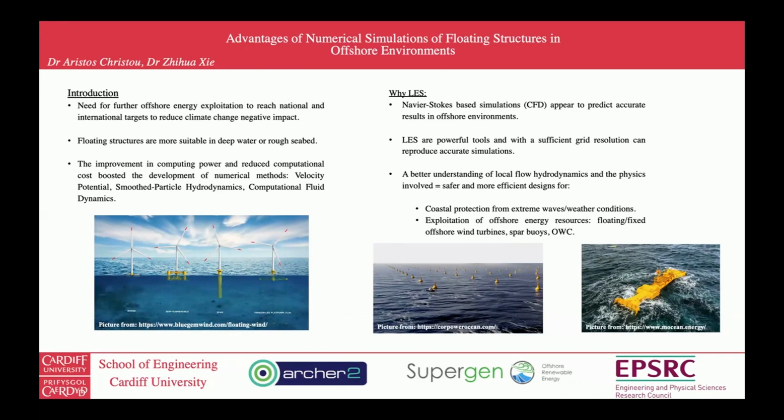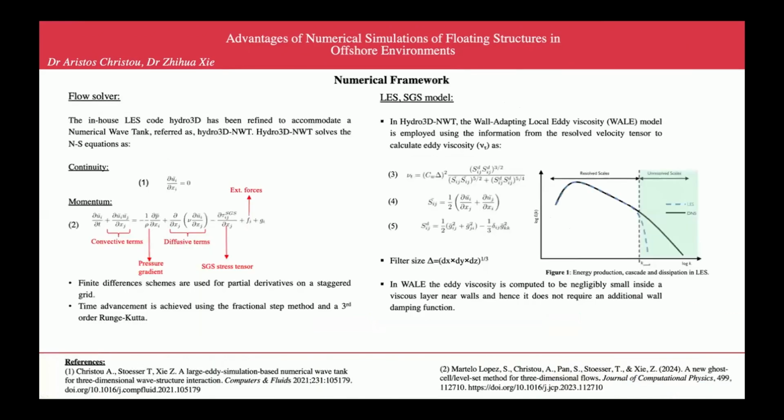And the big question is why LES? Obviously, many applications or many numerical wave tanks with different approaches can generate quite accurate results. But when it comes to strong wave breaking or flow separation or currents interacting with waves and all that stuff, then LES with a sufficient grid resolution can be a powerful tool, especially understanding the local flow hydrodynamics and the physics involved, which will end up giving a more efficient design for coastal protection or devices for offshore energy exploitation, such as offshore wind turbines, oscillating water columns, etc.